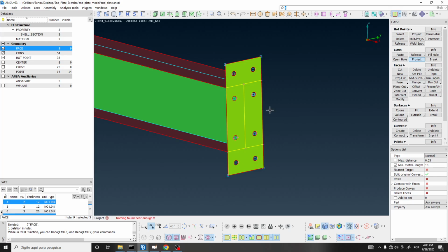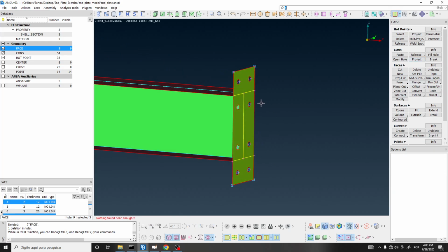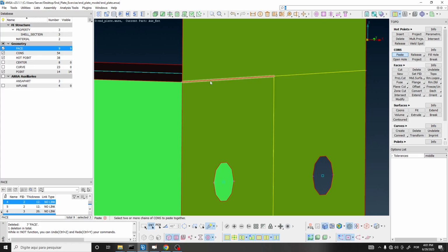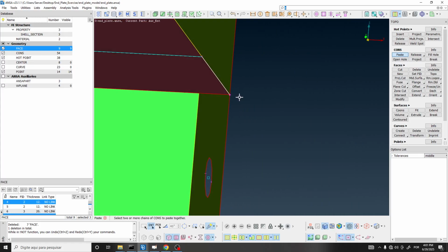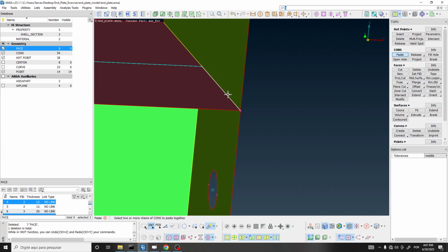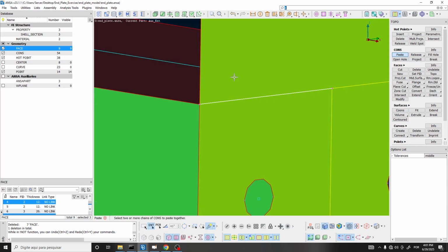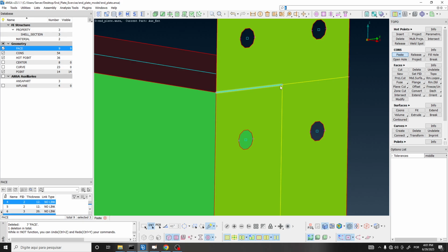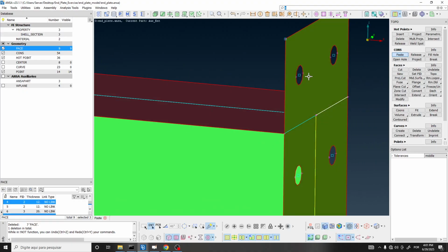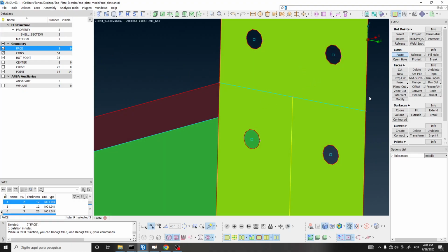Or, since we have already used the project tool, there is another manner. We have the paste tool here for cons. We can zoom in, actually select it, zoom in and select this cone. And I want to paste it with this other cone, this red cone, which is on top of it. But if I select again, the software is going to understand that I'm selecting the other cone that is positioned here. And middle mouse button, and now we have it as a cyan cone. We can do the same thing here, select these, and then select again to select the one that is on top of it, middle mouse button, and then it's cyan.